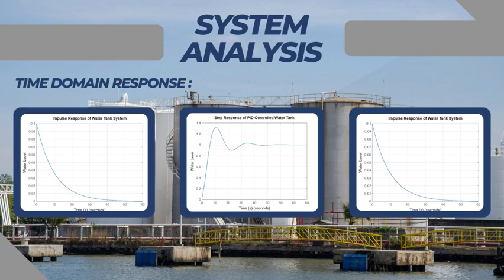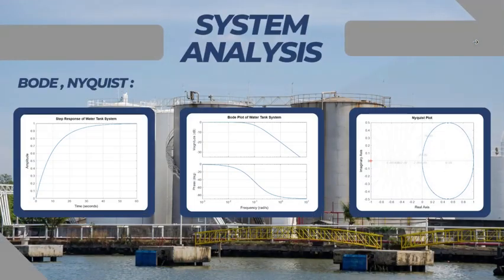2.2 Frequency domain analysis. Frequency domain analysis looks at the behavior of the system in terms of different frequencies using Bode plot and Nyquist plot tools to see how the gain margin and phase margin are, which helps us to know the stability and response at different frequencies.